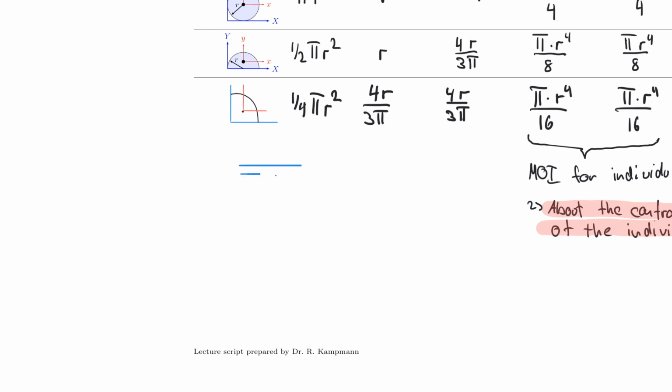So let's pretend, for example, our next shape will be an I-beam, and I'm just trying to draw a simple one for you here that is made of effectively 3 rectangles. And each of these rectangles has an individual centroid location, but also the entire shape has a centroid location. So I'm going to put this here as C total.